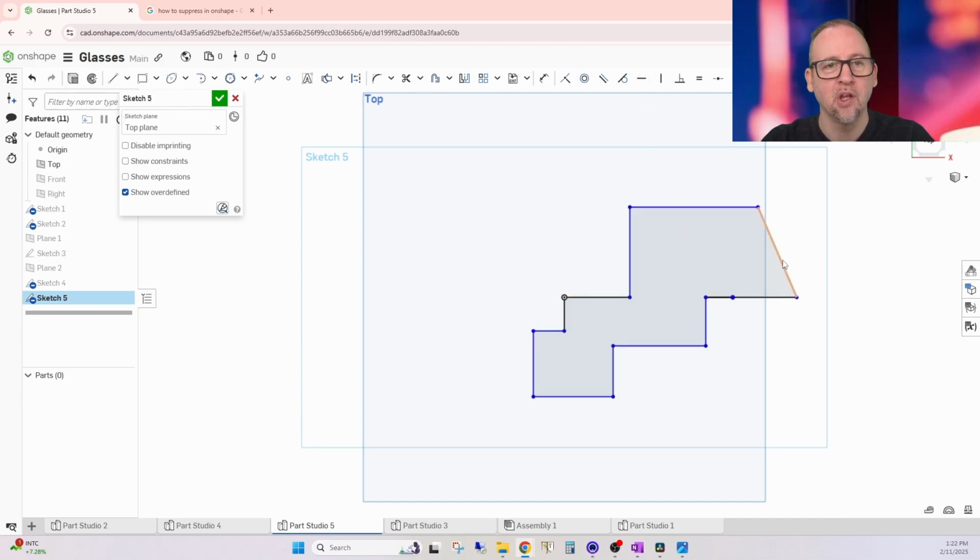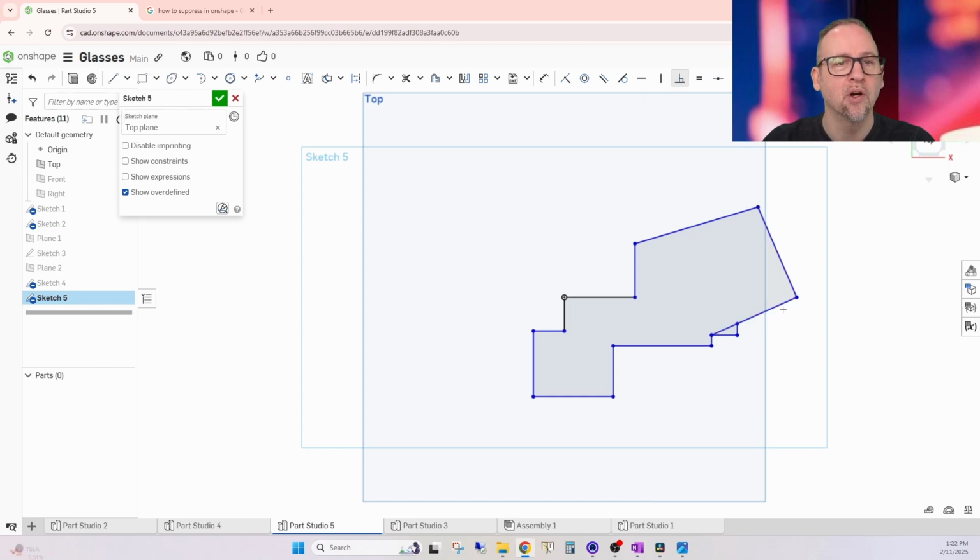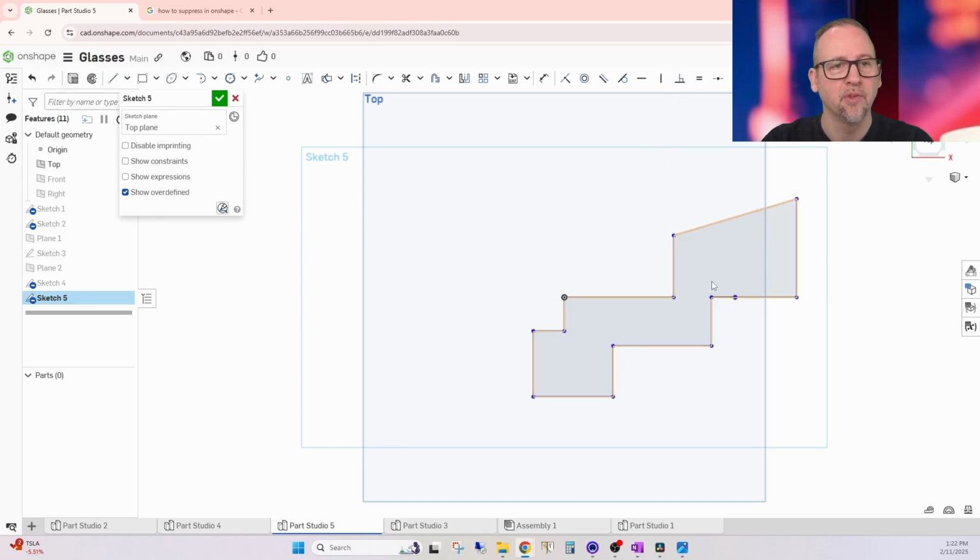And if we want this guy to be vertical, we do that. Okay, so let's undo, and we could also do perpendicularity. So if we use this one, and this one should be 90, it's going to fix one of those edges. If we want that one to be flat, then we would click on this guy. Let's hit out of that, and we're going to click on that edge, and we're going to hit this button right here. It's going to flatten that for us.